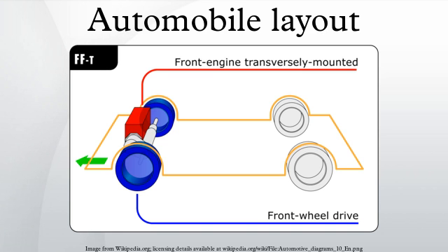The FF transverse engine layout restricts the size of the engine that can be placed in modern engine compartments, so it is rarely adopted by powerful luxury and sports cars. FF configurations can usually only accommodate inline-4 and V6 engines, while longer engines such as inline-6 and 90-degree big-bore V8 will rarely fit, though there are exceptions. One way around this problem is using a staggered engine.